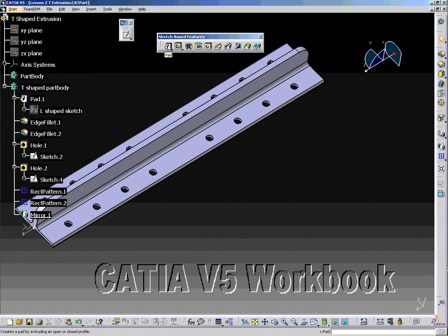The Solid toolbar consists of the Pad tool. This creates a pad or solid. The Pad tool creates a pad, otherwise a solid, by extruding a profile sketch. The profile can be an open or closed profile. Note that in most cases, closed profiles are easier to work with.